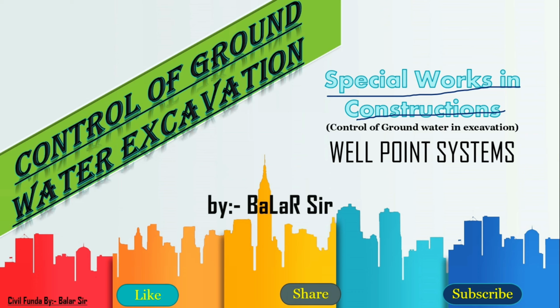In today's lecture, we are going to study the well point system. In the previous lecture, we completed two methods. The first is the open dewatering system, and the second is the sump and ditch method, which can be utilized when you have water above the ground level, that means on the ground level. But what about the condition when the water is lower down? At that time, we use the well point system.